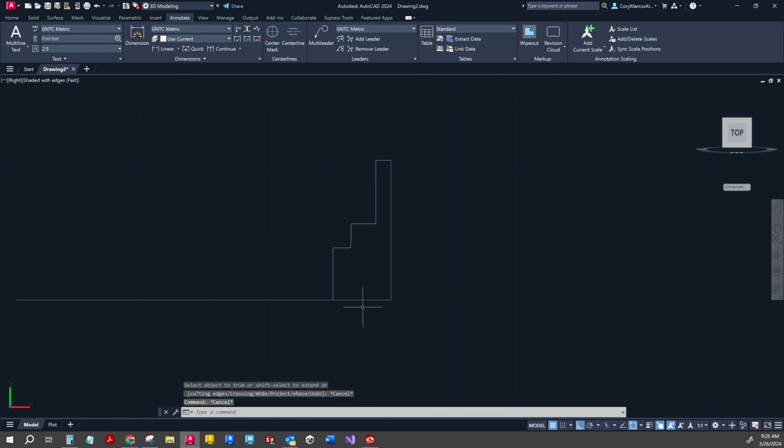So now we need to make the final neck of the part, which is shown in the section view as 32 or 30.5. And so rule of thumb, it's a tolerance. You're saying within a range, make it one of these values. This allows the people who are fabricating it to nail the part shape. So I'm just going to choose the top two values.